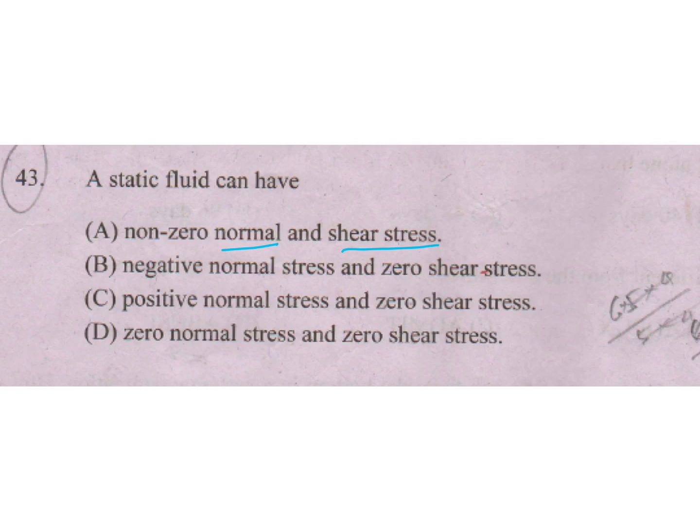This is not possible. This one also not possible. But negative normal stress and positive normal stress. In a static fluid, it's negative normal stress and 0 shear stress. B is the answer.